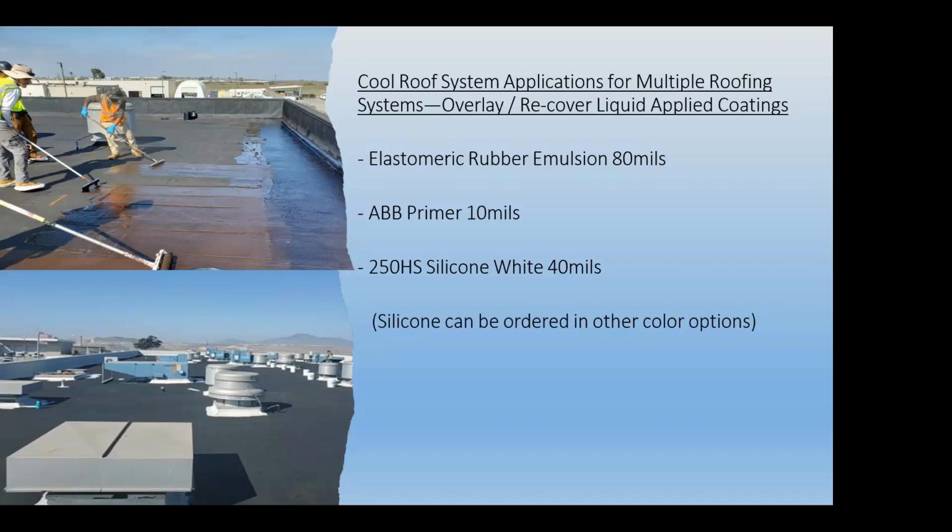You might have to shut down operations in that actual facility or move that work to another building. You don't have to do that with the overlay systems because there's no construction or demolition being carried out with an overlay. And you're also on average saving a third of the cost compared to the regular roof removal. So your roof removal could also require raising curbs, drains, scuppers, or adding more ISO board. This is going to add significant project costs.